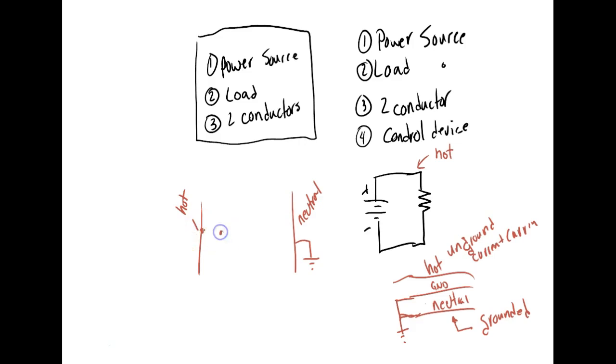You put a push button and come over here and do that. Well, that's illegal. You put your little dot there and draw that line, but that's illegal in motor controls. What you're trying to do is make a diagram that only you understand, but everybody needs to understand it. So dots are very, very important.